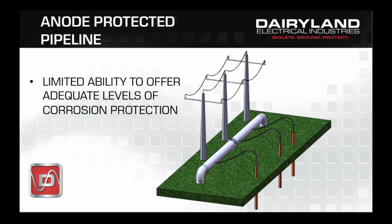This kind of scheme offers a very limited level of protection. The anode system itself has a fixed amount of current that it can move into the pipeline, and so its ability to actually drive the pipeline to the correct negative potential is really affected by the nature of the soil and the amount of surface area of the anode that's available to move current.